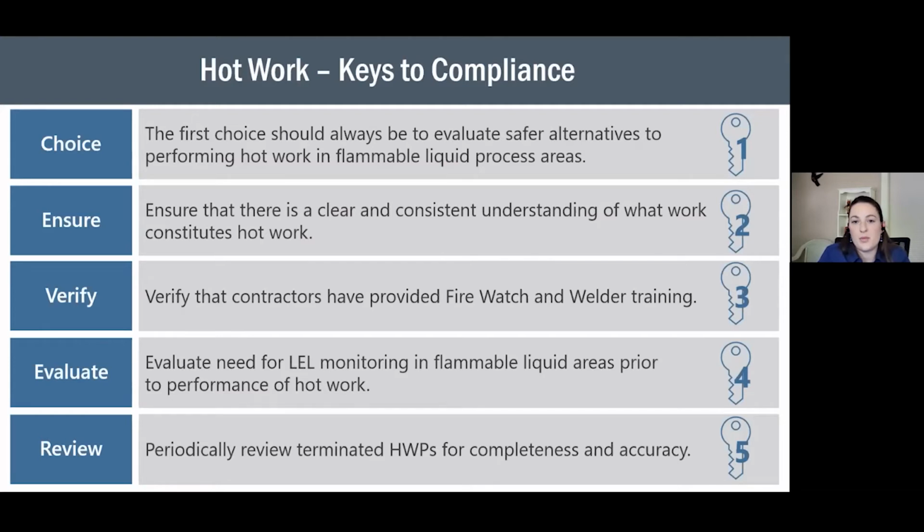If it's a flammable liquid area, there might already be LEL monitoring. If not, there are portable LEL meters. And when I say LEL, I mean lower explosive limit. So we're talking about the concentration of a flammable vapor in the air. So in some cases, it's appropriate to carry a portable LEL meter with you.